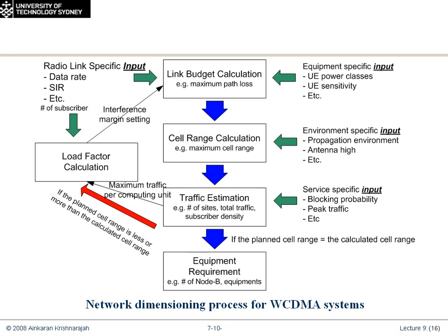You can't really have a 40-meter antenna in George Street, although you could have a 40-meter antenna out in Dubbo, and that would probably cover 5 or 10 kilometers. So a planning tool is not generally going to do something like that, because what you can do is you can mount the base station antenna on the side of a building, and you could get your 40 meters that way, but you wouldn't need a monopole, for example, to achieve that height. The higher the height as well, of course, the more expensive it is to construct that particular site. So although you've got the benefits of the height, you've got the cost aspect as well. So you've got this constant battle between the economics as well as the ideal radio scenario.